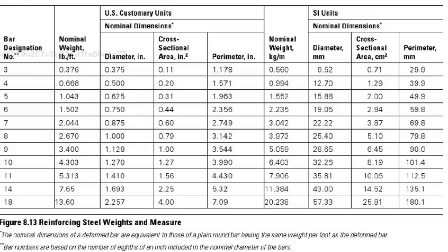So you need to be able to calculate first the number of bars that you need for a job, and then you calculate the weight of those bars, and you translate those weights again either into pounds if it's a small amount, or if it's a ton or more into tons, and that's how you're going to see the steel placed. Now when you're doing that calculation, remember that there's wastage and overlap.